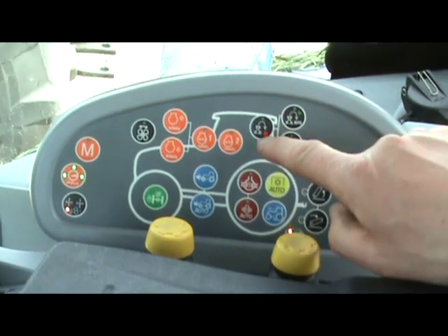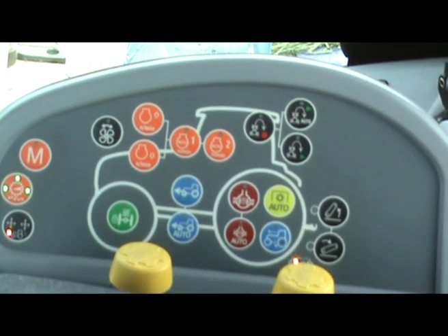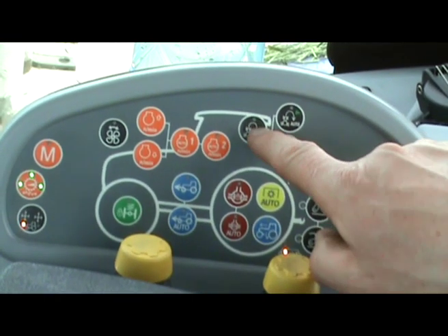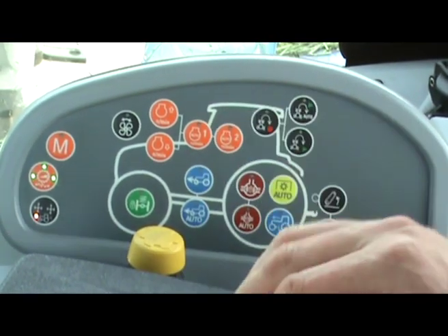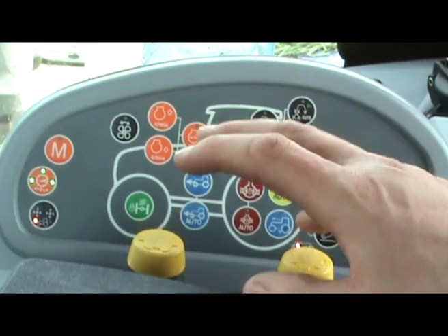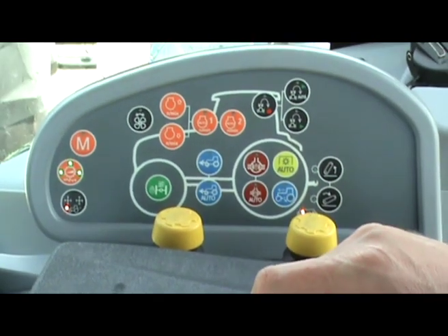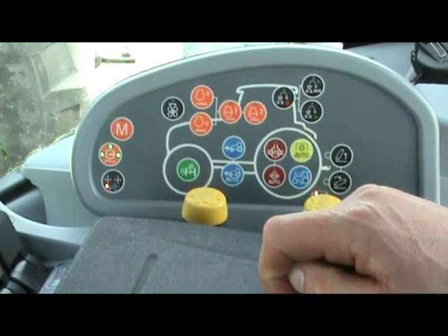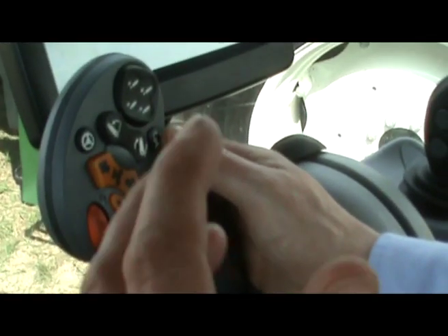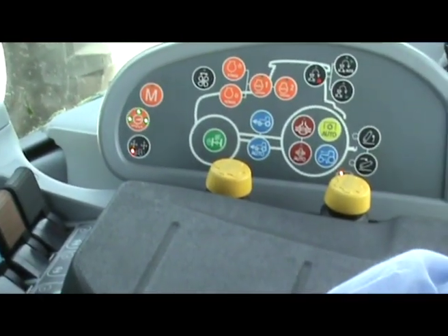The 3 buttons there, the record and play button symbols, are for a headland turn sequencer. So pressing the record while you're carrying out a headland turn, and the tractor records everything you do, and then you can store that and play it back on the playback either manually or automatically. So you come to the headland, press the button over here again, and it just runs through your headland turn. So for example, lifting the plough, turning the plough over, all done automatically.